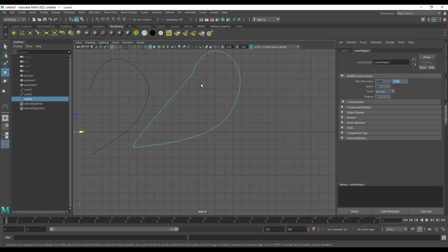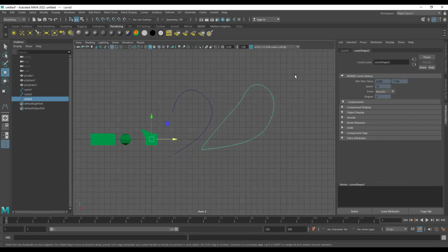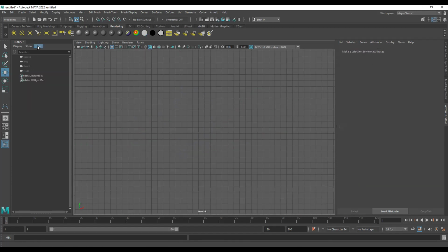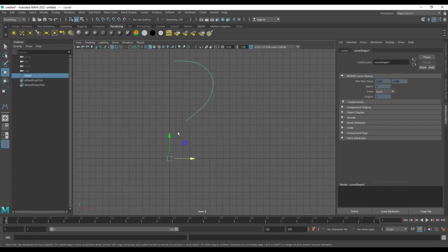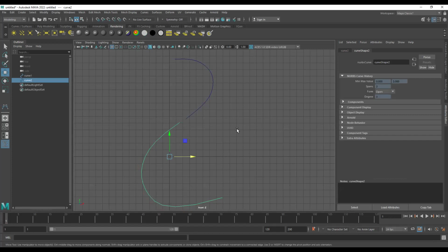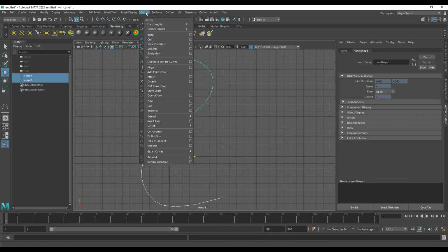Okay, why do we need to learn so much about this curve? You need to learn a lot because from the curves you can create a NURBS object. Suppose I have drawn this line and entered this curve. I finished it. I want to continue this curve, or cut this curve, or attach the curve, or flip the curve, or move the seam of the curve, or make an offset of this curve. Everything is possible by using this particular command called curve.